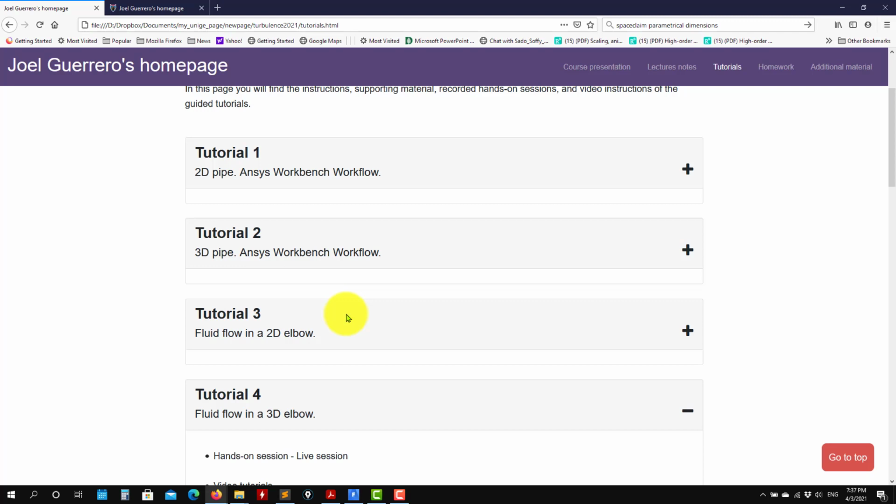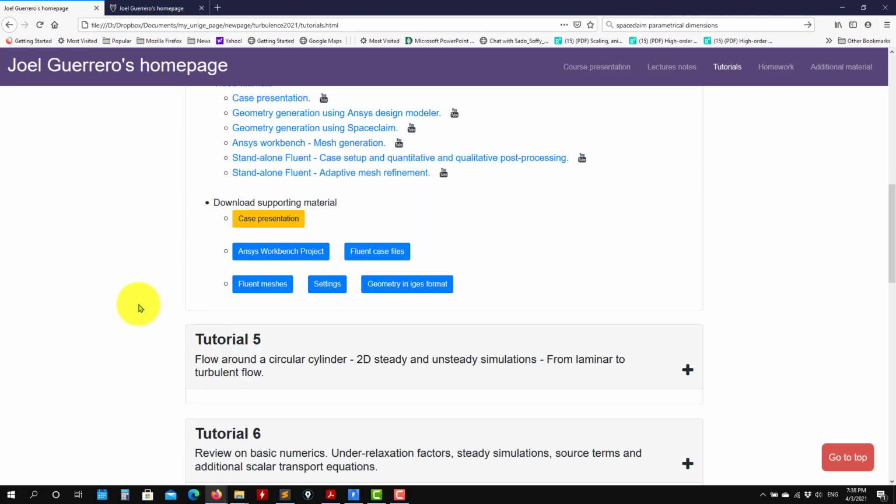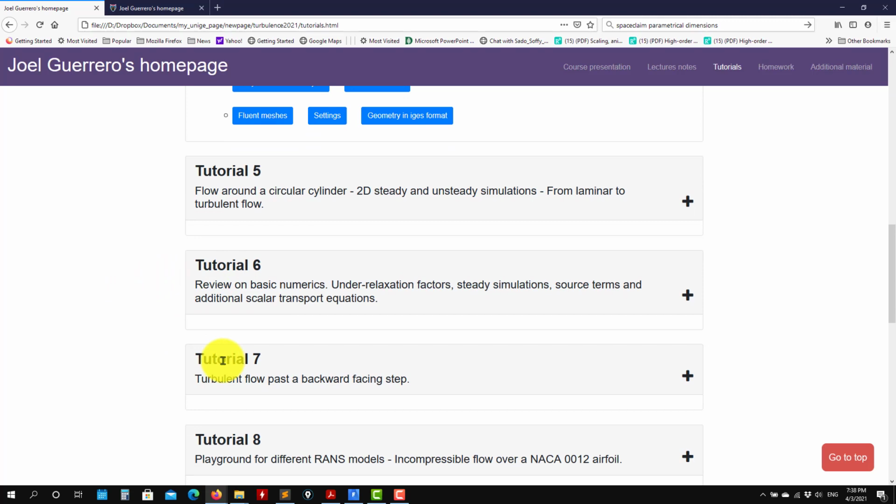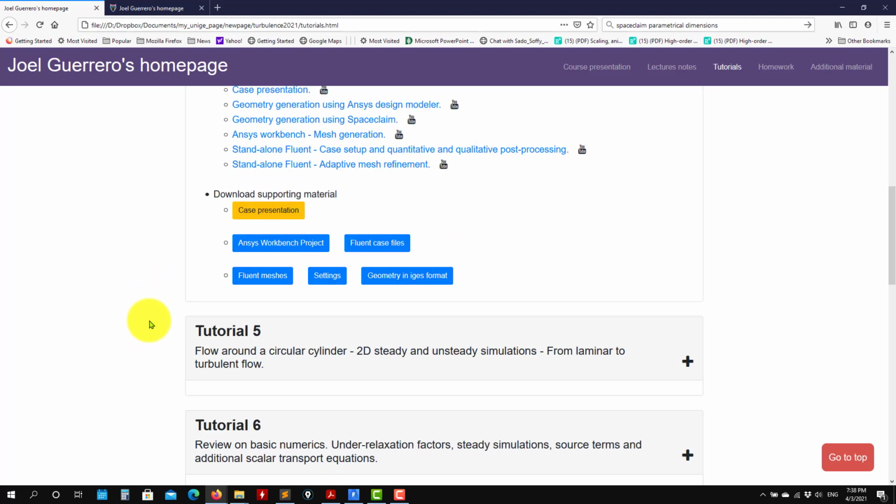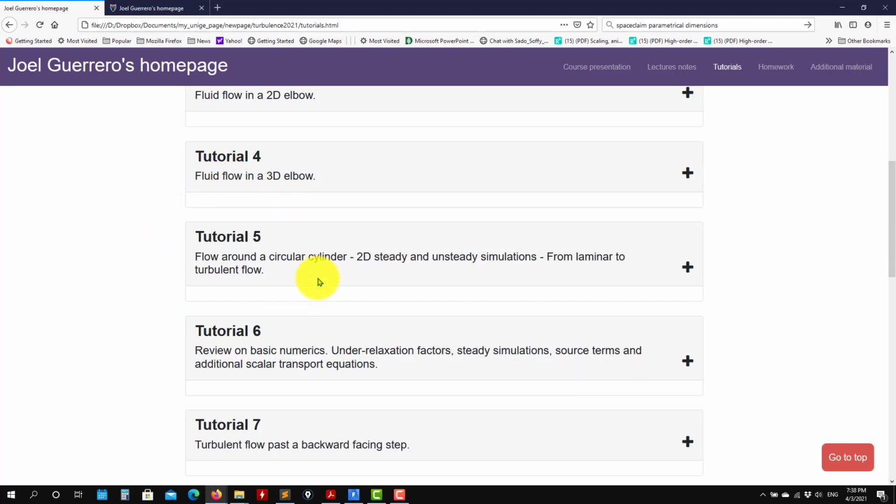Later we're going to go into other tutorials and see how to compute integral length scales using the turbulence quantities. We know that we can use a combination of k-epsilon, k-omega, whatever, to get an idea and then build meshes focused on those quantities. That is called a precursor simulation. We'll start to do that from tutorial 7, 8, but first we have another tutorial.